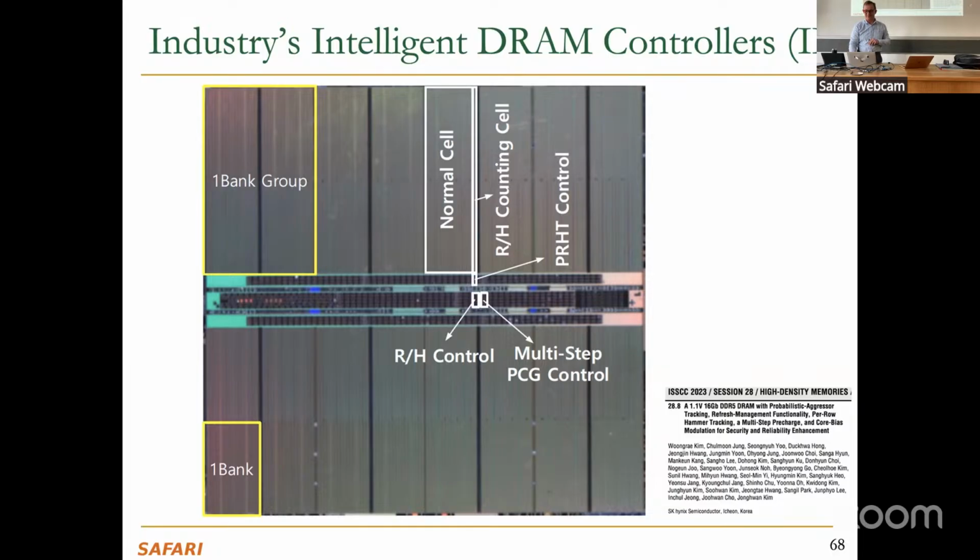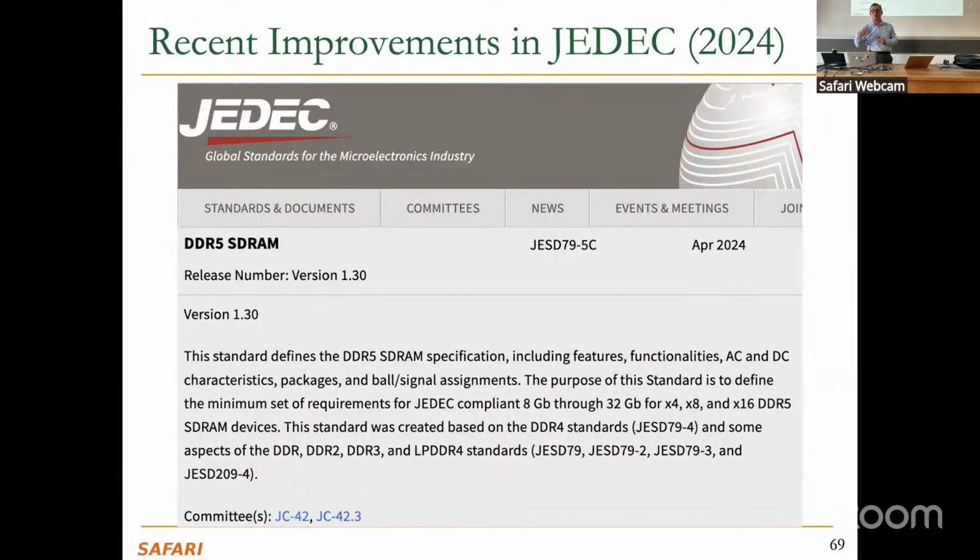Okay, great. But this is the gist of the solution developed by a major manufacturer, and they actually manufactured real prototype chips to look at that. There are, of course, potential issues over here, which we will discuss again in the RowHammer lecture, but this sort of solution was recently standardized in DRAM standards. JEDEC is the industry standardization body that standardizes a lot of things in DRAM, memory, storage, etc. And it's called per row activation counters right now.